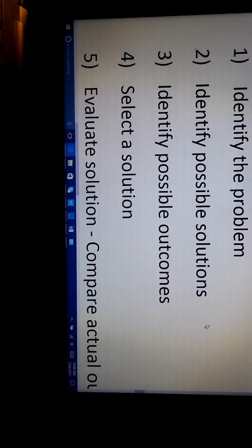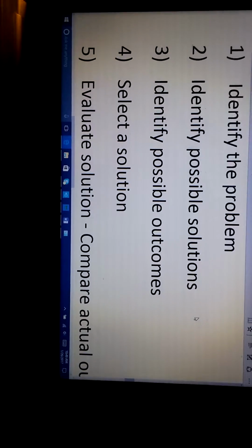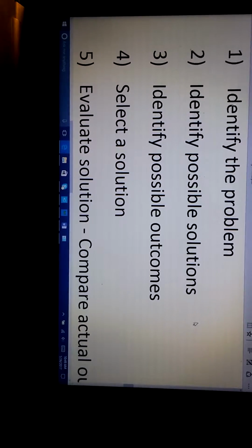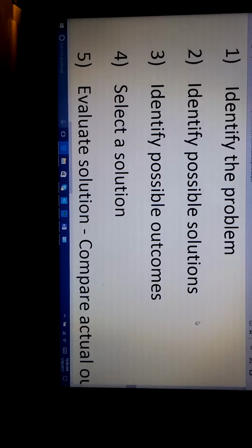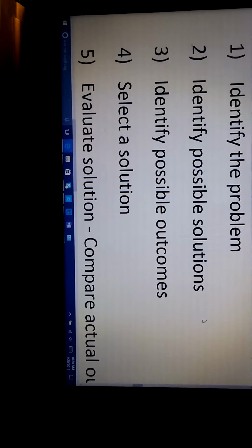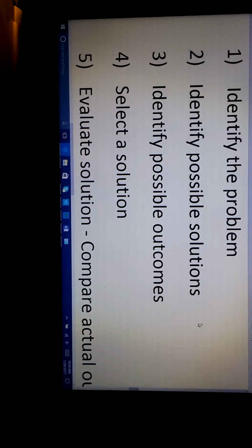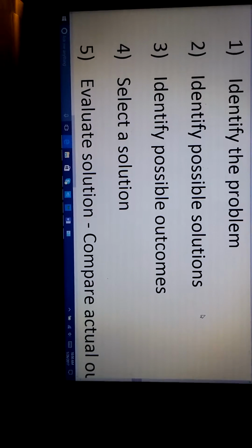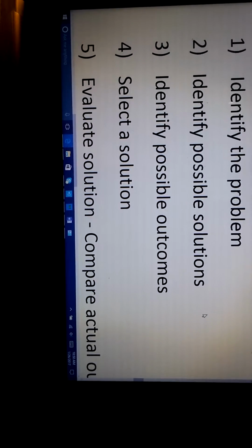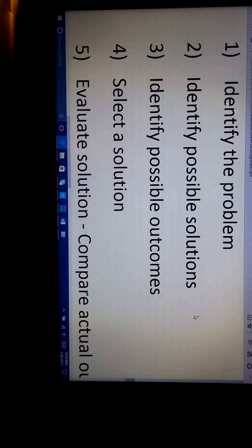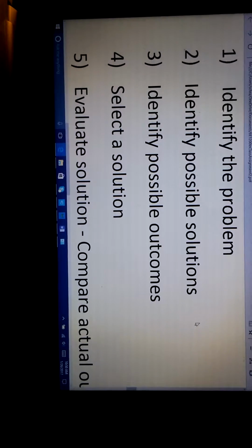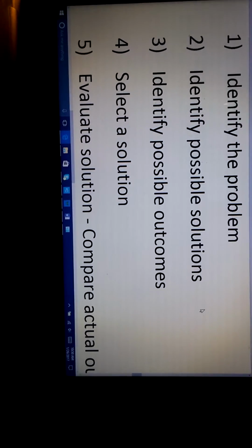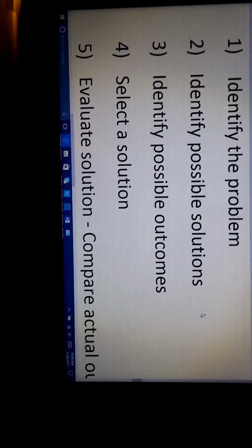Well, first we have to identify what is the malfunction. Is it that traffic is holding up? Is it that somewhere in the computer programming it's not functioning as it should, but the people in the outside world, the traffic, don't even notice it? Like, for example, when a detector goes out, a signal will go into an override mode. And what that is, it's like a pre-timed, pre-programmed mode.